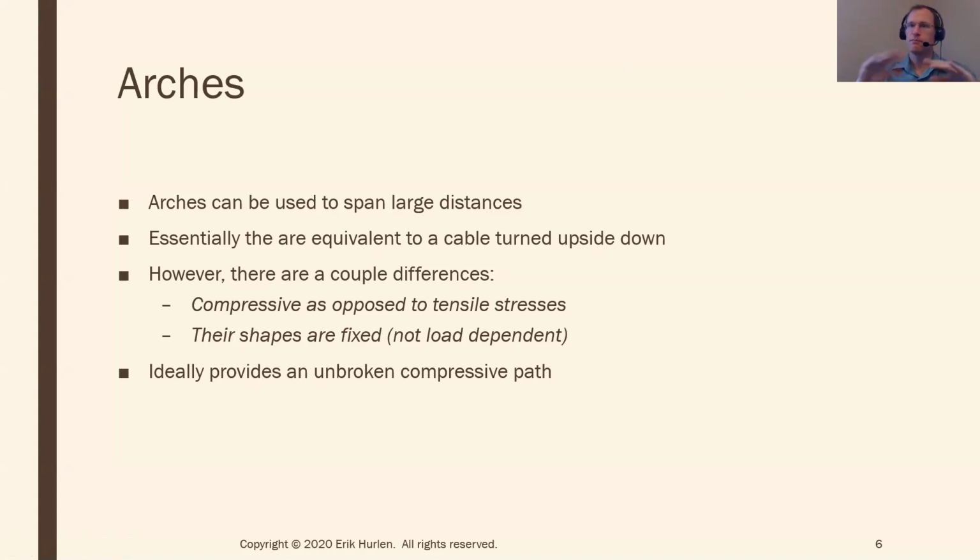They push up from the bottom, and their shape is essentially like an upside down cable, if you think about it. So again, they provide compressive as opposed to tensile forces. And then their shape is fixed. So the biggest difference, other than it's upside down, is the fact that an arch isn't going to change its shape. So any sort of cable, if I come along and hang a new weight on that cable, it's going to kind of change its shape and all the different angles.